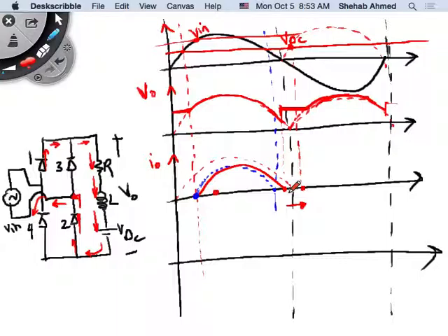To the left. You're opposing current flow, right? It's the opposite of what increasing the inductance would do. What would increasing the inductance do? Help maintain current flow, so it would move it to the right. Decreasing the DC source would move this to the right. Increasing the DC source will move it to the left. Decreasing the value of inductance will move it to the left, because it becomes more like a resistor case. Right? Okay.